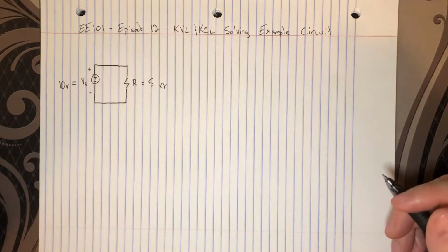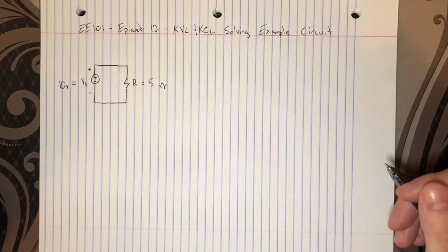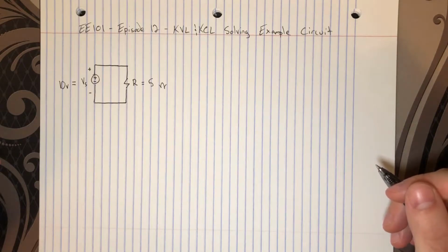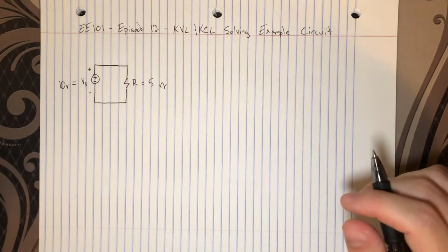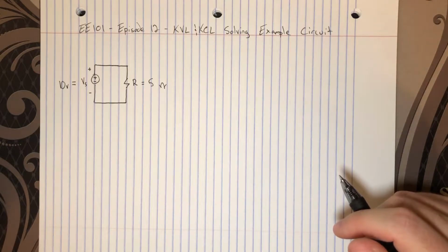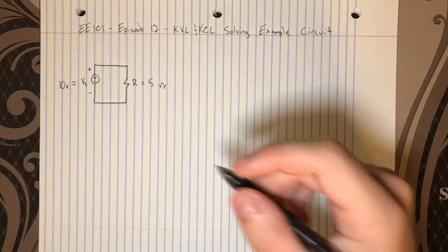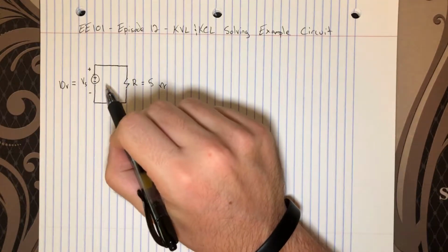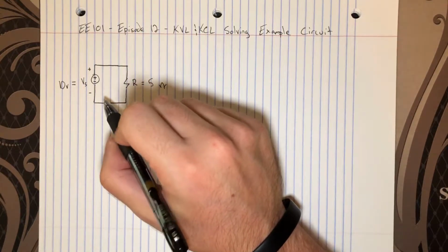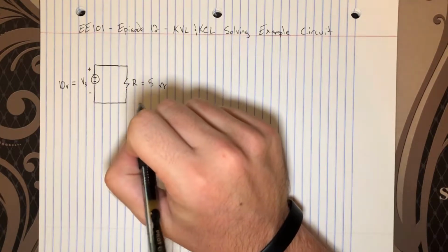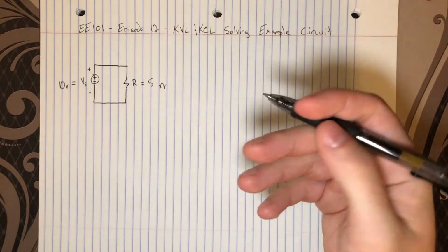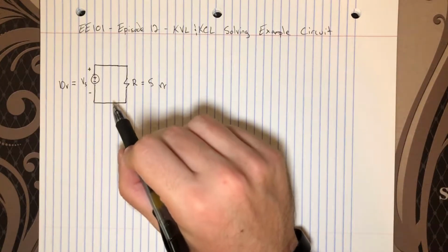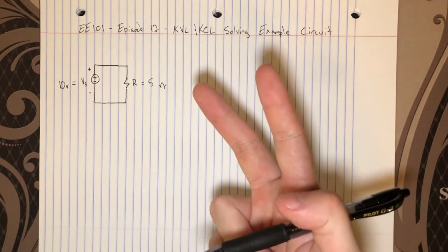So to begin, we've got a voltage source, so it's probably a good idea to try and identify as many voltages as we can in the circuit before we move on. And the first thing you want to notice is the fact that these two elements are connected together via ideal conductors. So there's two ways. Let me just say, I automatically know the voltage across this resistor, and there's two ways that I know it.